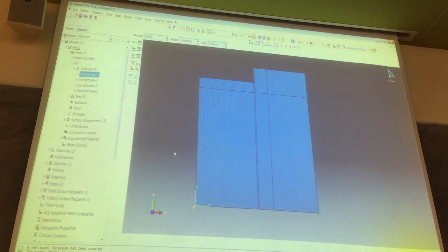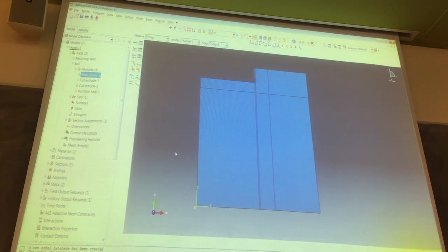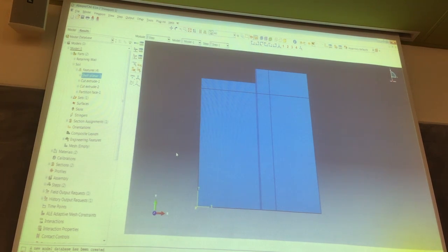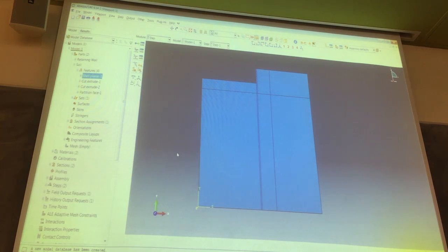I think it's a part of the project to get the shear and moment of the wall. So you can select those. First of all, you activate that part so the software stores all the output for the shear force and bending moment. And after that, you define a path like before we defined it for a beam. You can select the nodes, and after that, get the output for those nodes for shear.